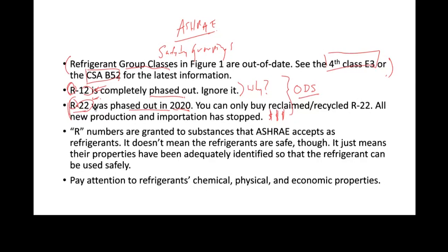And so some of the ASHRAE refrigerants are highly toxic. You get a little whiff of it and it knocks you dead. I do think that hydrogen sulfide or sulfur dioxide, one or the other, are refrigerants that are given R numbers. So you can see that there are some nasty things with R numbers. We've got something like R290, which is propane, and highly flammable, right? And then we've got other ones that are immediately dangerous to life and health for different reasons. So anyway, that's what ASHRAE does.